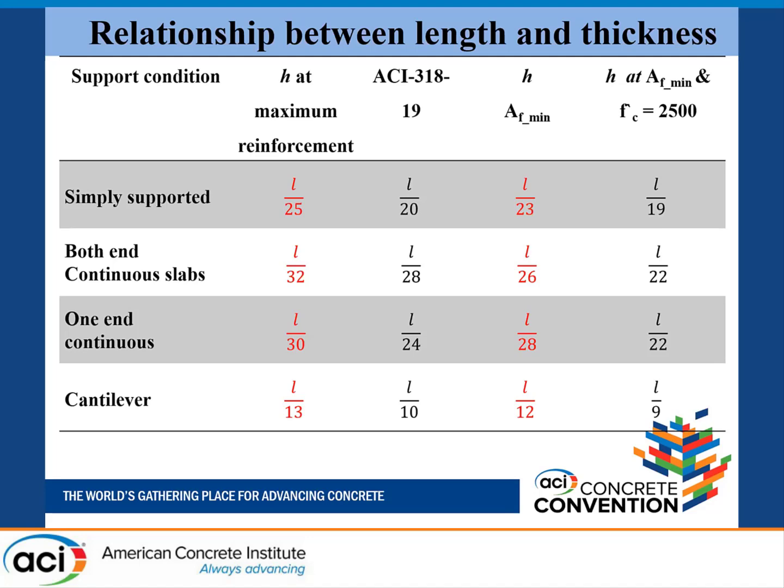In order to understand why GFRP has slabs of lower thickness compared to steel, I actually decreased the concrete strength f'c to 2500 PSI, and I used reinforcement only for flexure, and I ended up with a thickness more than steel. So if you decrease the concrete strength to 2500 PSI and you use the reinforcement only for flexure, you will have more thickness.